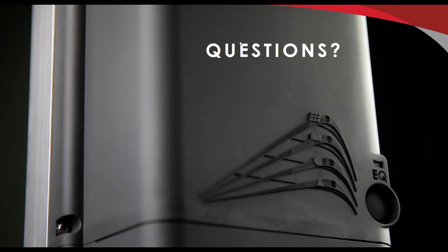Okay, Brad asks if the meters will show reverse AC output or grid feed. The output from the grid-dependent inverter shows up on the SkyBox as a negative load, Brad. So when you have a grid-dependent output that is greater than your protected loads, SkyBox sees that as a negative number on the loads panel, and then that shows up on your grid output as selling back to the grid from your loads.